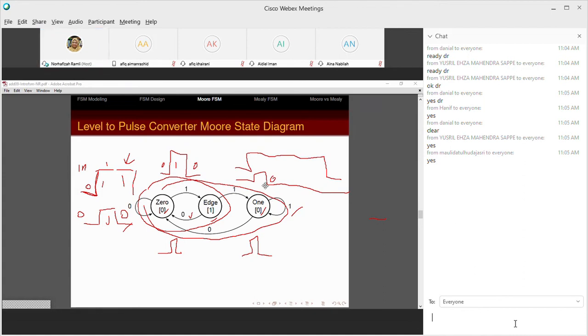But if you start receiving 0, here 0, then obviously if you see 0, the next thing you expect is 1. So that's why it has to go back to the 0 state, so that you can start looking for the rising edge. Okay, that's why you need the third one. Normally you detect 0, 1, kind of like you detect a two-bit sequence. You have to detect 0 and 1. That's why you need 1, 2, and you need the third one to settle.